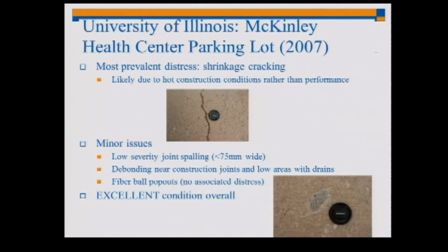One other problem is mixing the fibers. These are 40 millimeter fibers, which I'll show in a second, but occasionally if the contractor or the material supplier doesn't mix the fibers properly at the plant, you find this later on. Now, it doesn't really cause major problems, but you can see it on the surface, so it kind of looks bad. Overall, though, both these parking lots really have no distress. Again, they don't have any trucks passing them, so one wouldn't expect that.